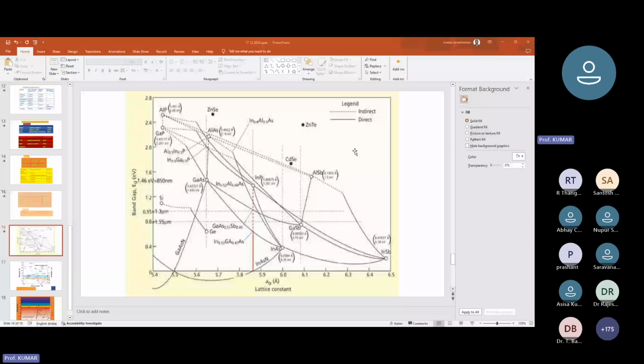So all these things can be in some form clubbed, which is called as tandem solar cells. And this, in theoretical terms, can produce an efficiency close to 87%. Though it is not practical, people have shown in space applications, these tandem cells can produce something close to 52% efficiency. These are some of the relatively standards which are being used in current segments of solar panels used for